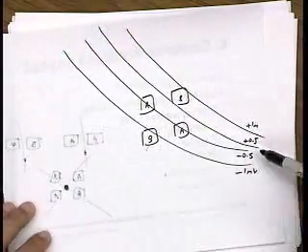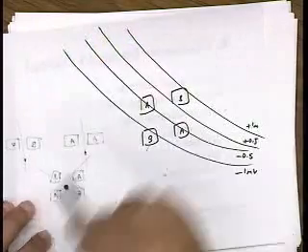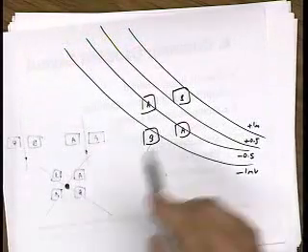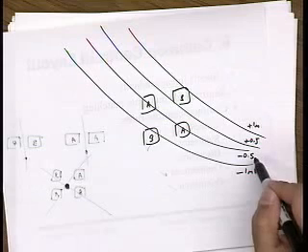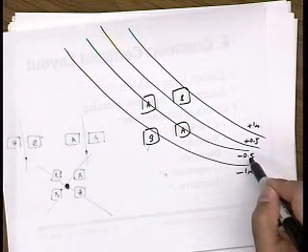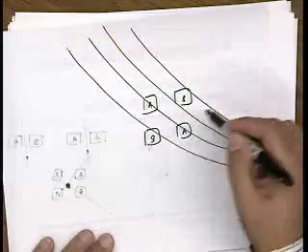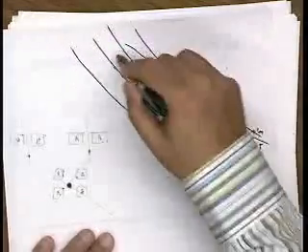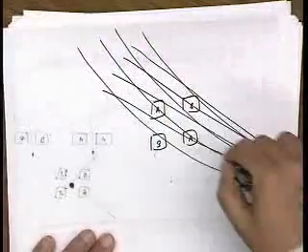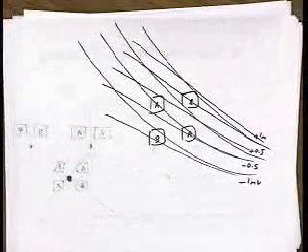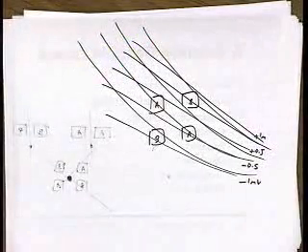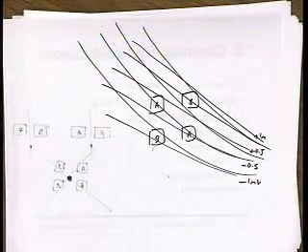This device, on the other hand, falls on a constant Vt contour, so in this case, it's going to have half a millivolt less Vt. Well, I really exaggerated this gradient here. If this is a tiny device, these are actually going to be straight lines. And for straight lines, this common centroid would actually cancel out any kind of Vt mismatches.